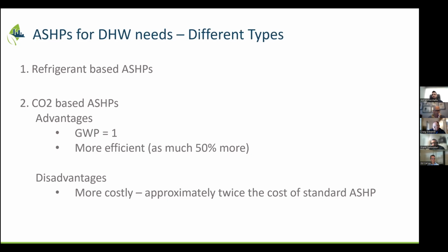In general, we're building a lot of new buildings, and as I said, our standard is 100% electric. So our starting point is if the loads are really small for domestic hot water, we'll just put in an electric resistance tank. And then if it's a medium type load, like a fire hall or an operations workyard, then we'll typically put in integrated heat pumps, the ones you're talking about with the heat pump on the top of the storage tank.